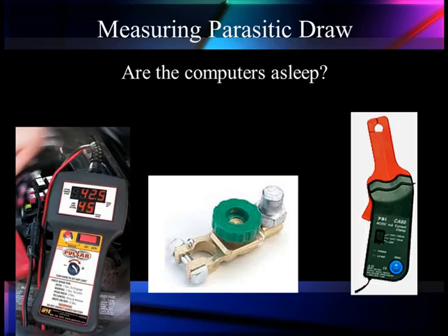On modern vehicles, we have computers that stay awake all the time. If you have a keyless entry system, it's a computer that's going to unlock the door when you push the button. It has to be awake. You need to get a good spec. We expect to see it drop down to 50, 75 milliamps in most cases. There are a few vehicles with lots of computers, really elaborate. 100 milliamps is not abnormal.